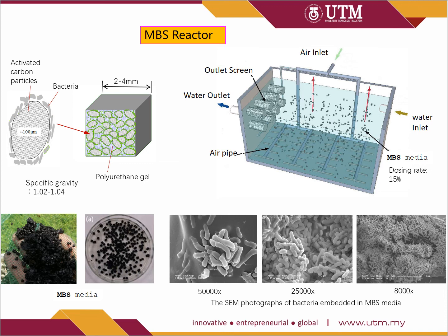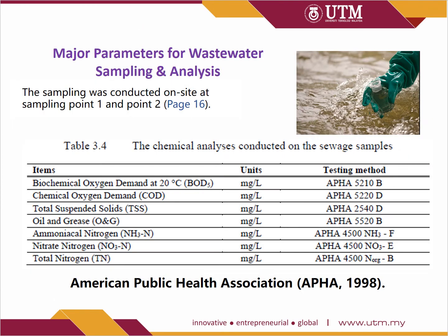Okay, so with this system, this kind of polymer is quite cheap, but the activated carbon and the microbe inoculation will be the main cost. When we suspend it in this moving bed, it will efficiently treat the water.